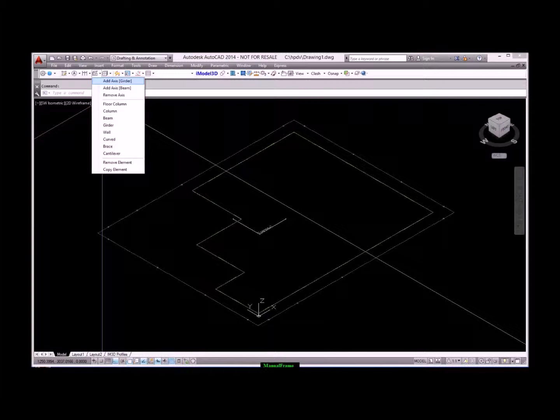Frame name must be unique if you plan to have more than one space frame per model. It is recommended though to have one space frame per drawing. It is also worth mentioning that a space frame is one entity even though it consists of many elements, as we will see later. Also, you can model your building without generating any space frames, however, you will not be able to apply loads nor will you be able to do structural analysis later on.